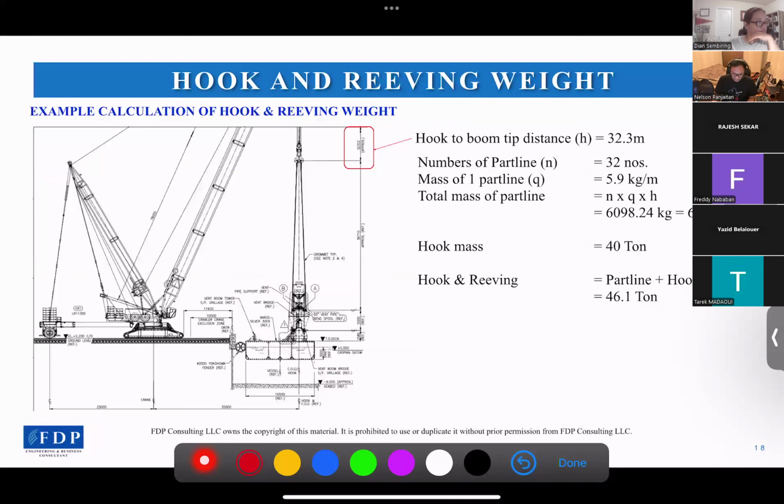And this crane is going to be used to lift a structure with a rigging height of 36.71 meters. The lift point distance to the bottom of the tracks is 2.58 meters. 2.58 is pretty small, yeah. 2.58 meters plus 5 meters here, so the total will be 7.58 meters.